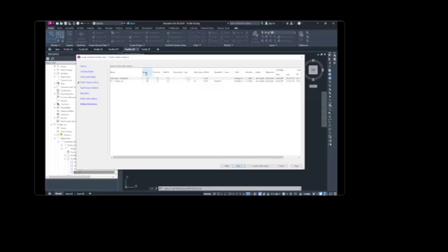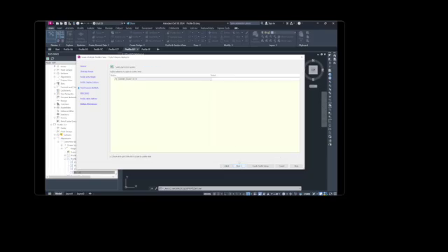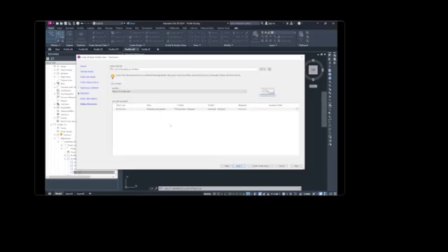Profile display options page, ensure that the draw checkbox is selected for both profiles. Click next. Good. Open the pipe network display page. Click next. Data bands page. Under selected band set, we're gonna select EG, FG elevations and stations.